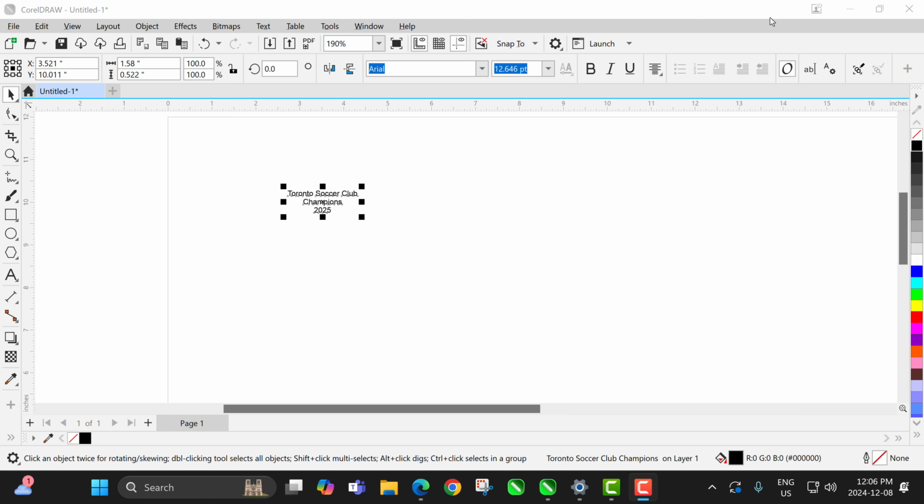In today's lesson, I'm going to use CorelDRAW and Ruby to show you how to set up the 12 by 24 sheet so that we can send it over to the laser machine. The example I'm going to use is a 1 by 3 plate, because this is a standard plate size that we would see in the trophy industry, and this is where we would use a lot of the Trotec lasers.